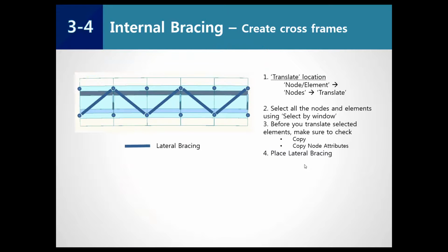And this one is for the variant type lateral bracing. As I mentioned before, two nodes are located on the steel top flange. So first go to top view, and you will see these views, and just connect those dots to complete the variant type lateral bracing.